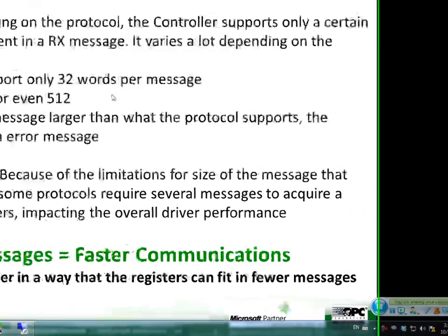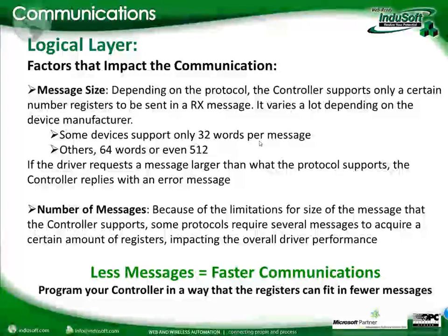So, some factors really impact the driver communication performance. The message size is defined by the protocol itself. So I cannot send to the PLC a message that the PLC will not be able to respond to. And who defines that is the protocol used to communicate with that PLC, or the protocol that PLC supports. For example, if I'm talking Modbus and my PLC supports only 8 registers per request, if I request 11 registers, the PLC is going to fail. It's going to send me a reply saying, no, I cannot reply that to you.